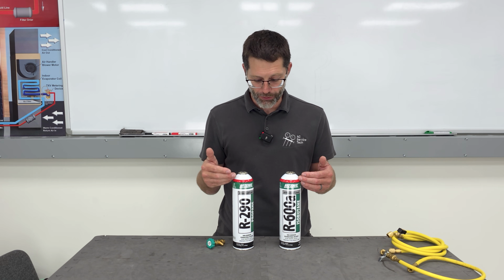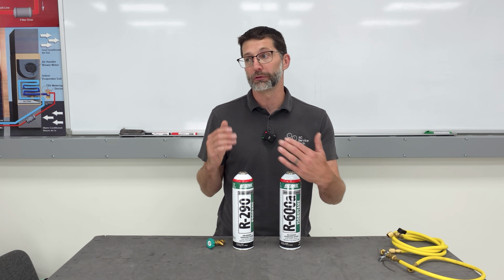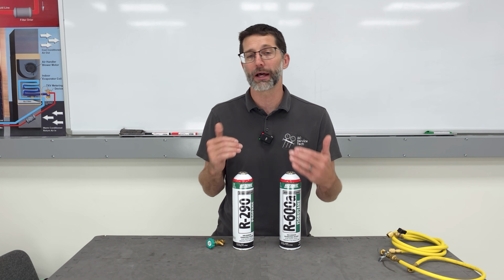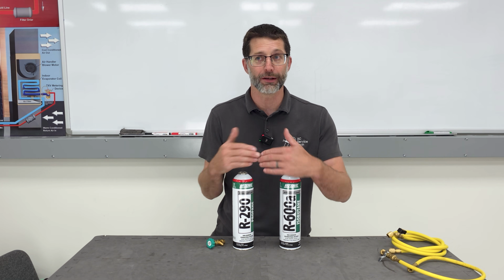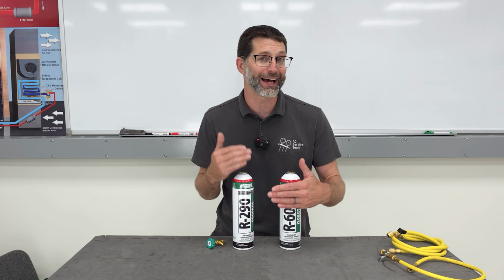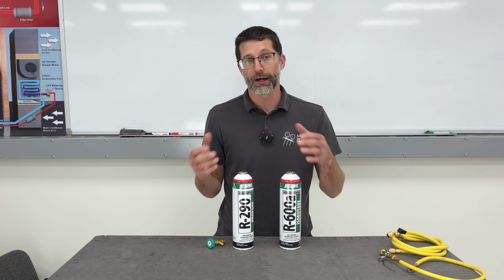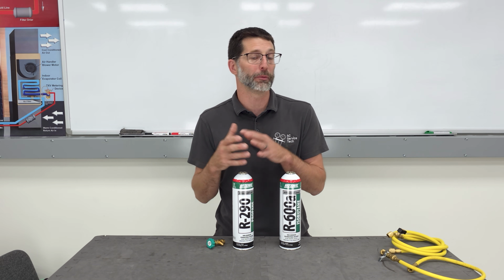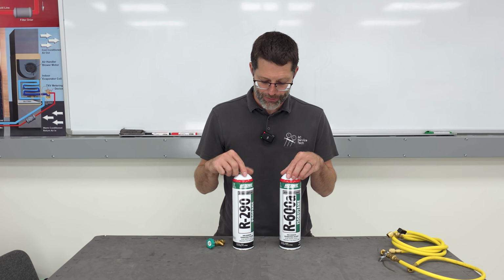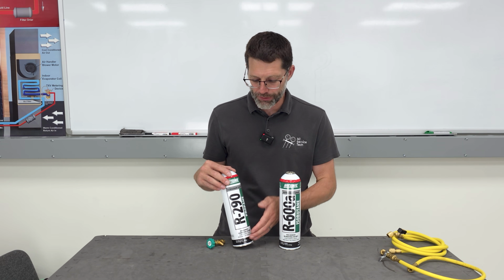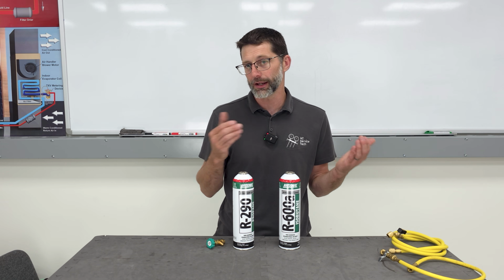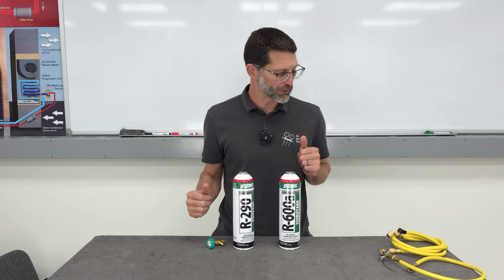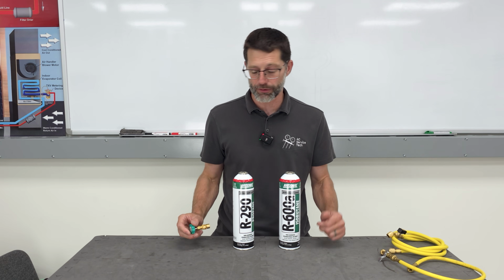But these are presently used in, say, refrigerators and chest freezers, things that don't have a whole lot of refrigerant inside. So if they did leak, say, the 3 or 4 ounces that they had out of the system, it would dissipate with the air in the room. And so there wouldn't be necessarily a flammability concern there. That's why these are in smaller bottles, say, a 14-ounce bottle like this, or a 14.8 ounce bottle here. So you don't need a whole lot of refrigerant in order to charge these small systems.